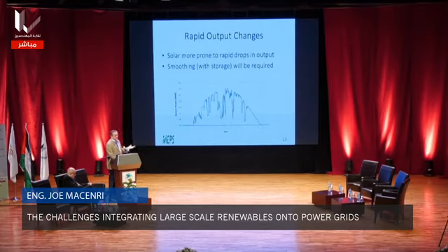So for the likes of a 40 megawatt solar PV installation, it may well have to have 20 megawatts with 4 megawatt hours of storage in it just to do the smoothing. Because typically utilities don't like to see the output change, the ramping down of the generation, by more than 10% per minute. That would be a typical sort of limit that utility operators want.